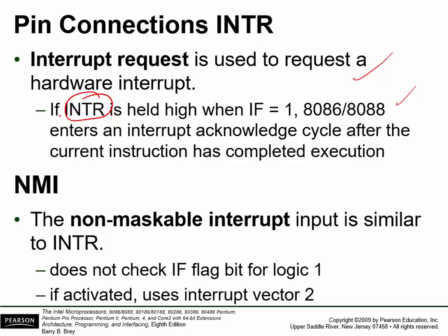While I'm talking about interrupts, there's also something called polling. Polling means that I'm not relying on interrupts. I'm going around checking all the time. That's the opposite of an interrupt, in that the nurse gets up from her station once an hour or once every 30 minutes or whatever the protocol is, and walks around and sticks her head in each of the rooms, sees whether the patient's still breathing. That's polling. She's doing her rounds and checking.